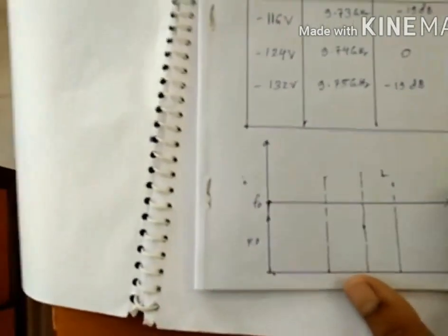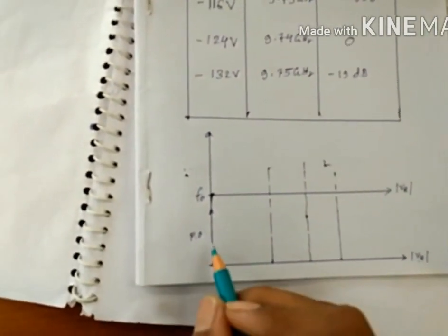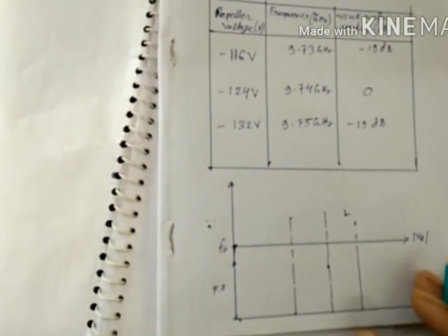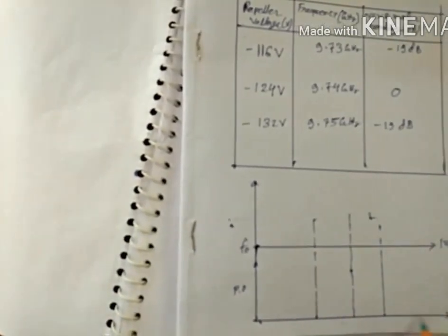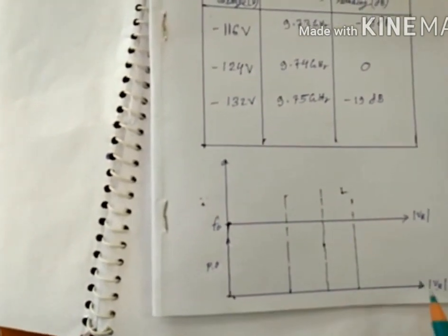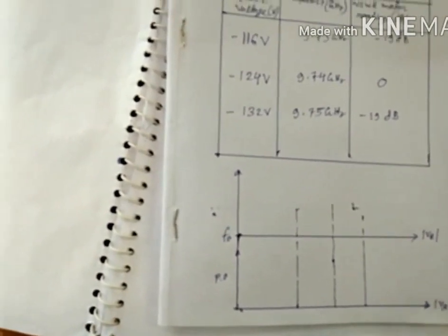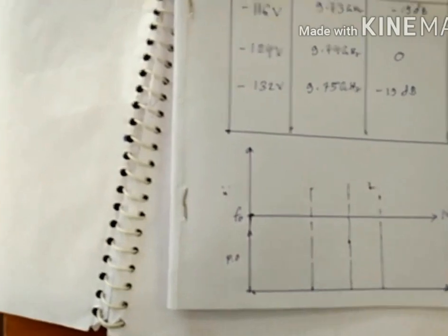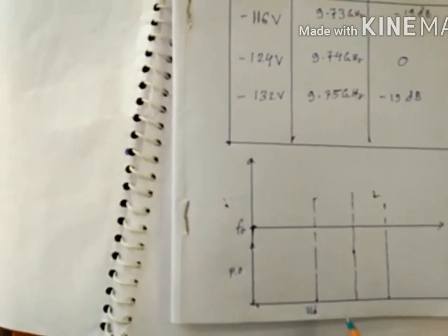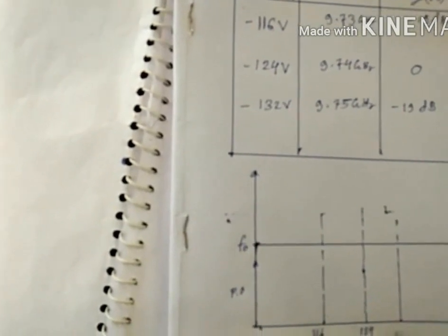Now plot the graph. One is the mode of repeller voltage versus output power, that is the VSWR reading. Output power means the VSWR reading. So the x-axis reading is repeller voltage and the y-axis is power. Then repeller voltage 116 here, 124 here, 132 here.